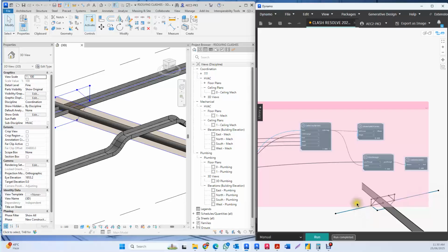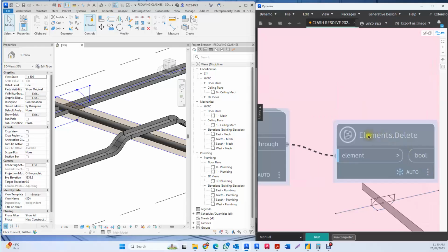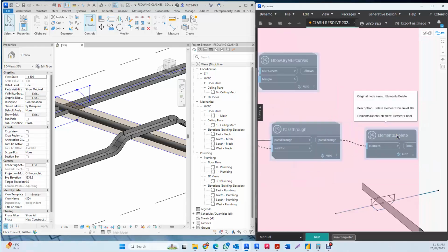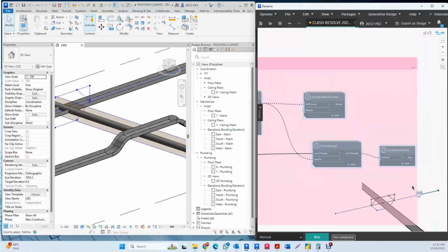It will give you an error in this area and this area and tell you this is a duplication of the material in the same place. So to avoid this, we have to delete the element. Which element do we delete? The initial element. But we need to delete this one after creating, not before.